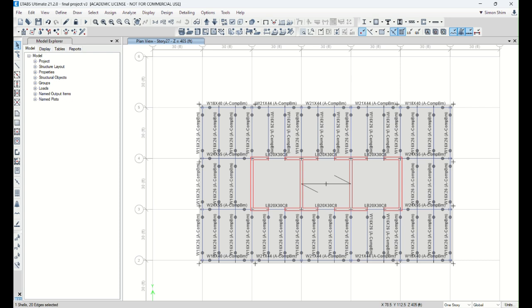Here, basically, we have a nice backbone. We intend to use the concrete core wall, the shear wall, as our backbone. Columns and girders are relatively minor. Even if you use a big girder, its contribution is relatively smaller than the concrete wall. Concrete wall is much stiffer than steel, which means more economical. So remember that.